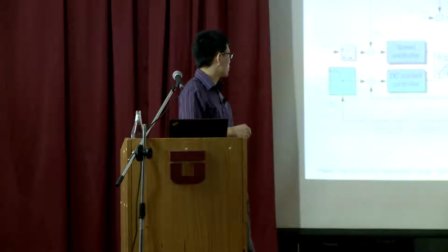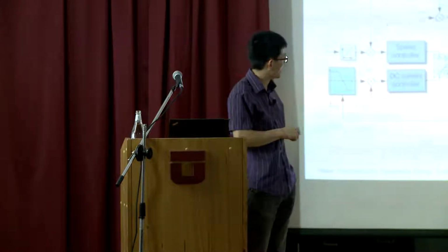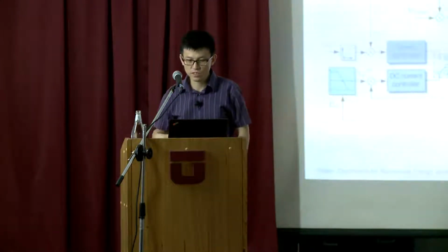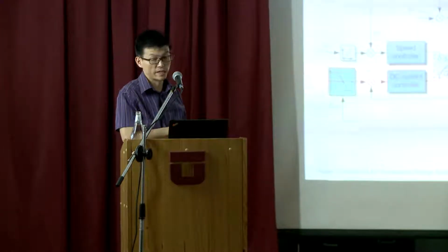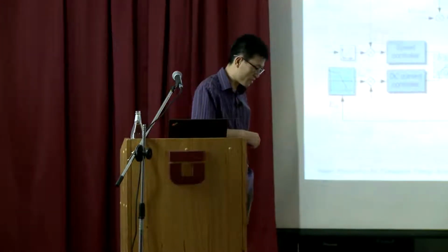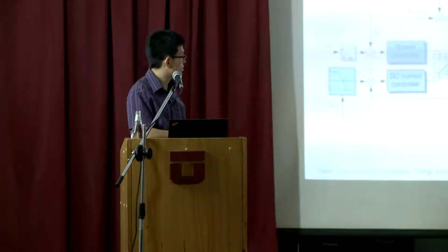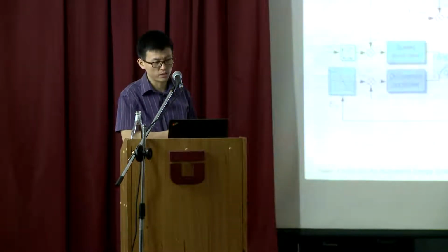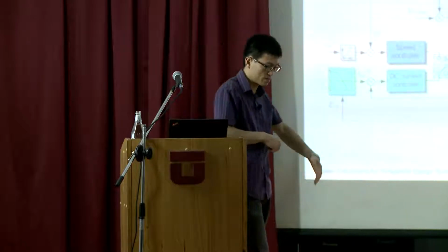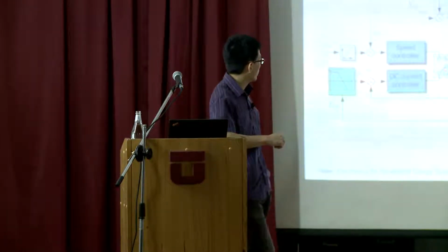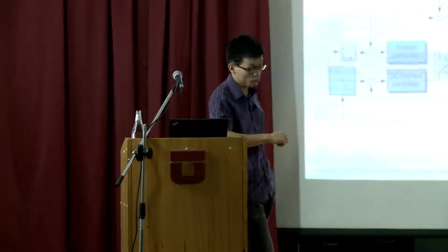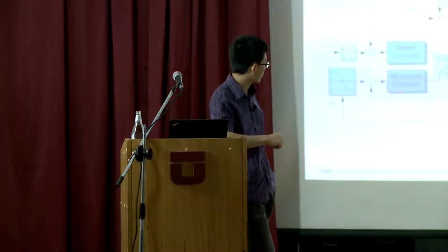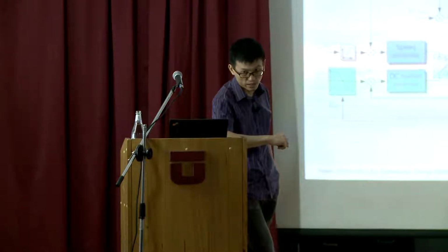Afterwards, there will be a flux controller. If the machine is running very fast, you want to control the flux, so you have the flux controller to give the ID reference, which is the flux reference. Then the power refers to IQ, and is also proportional to IDC on the converter side. So you have the DC current controller to give you the IQ reference.